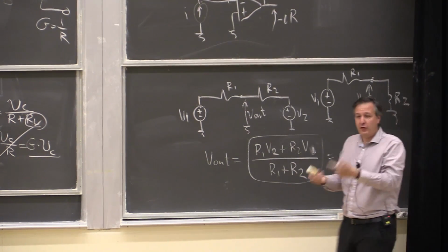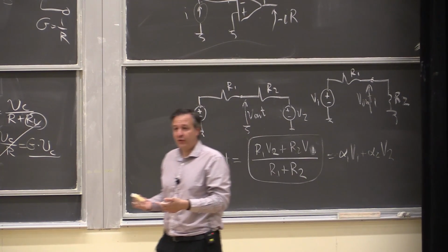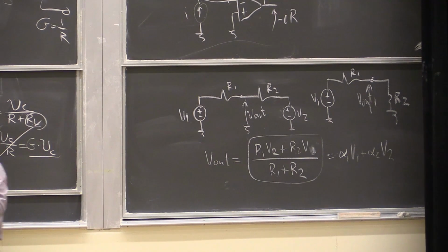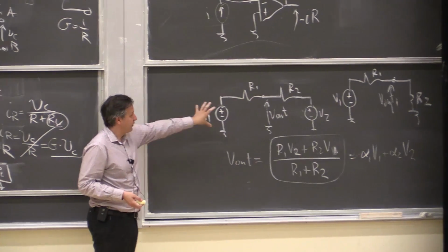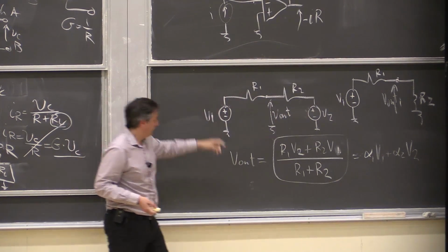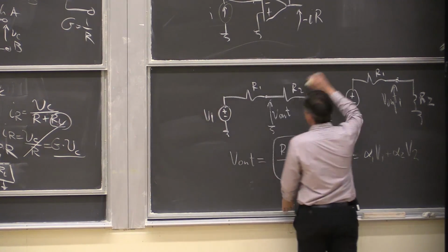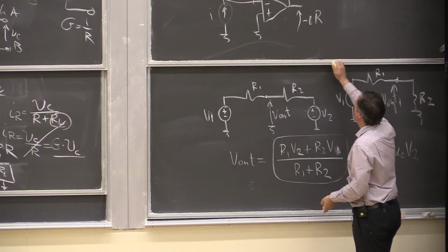So if in your problem you're asked for coefficients that are greater than 1, you need some sort of amplification, either before, if one of the coefficients is greater than the other, or after, so that you can gain everything up. So there are some small things to think about. There's another summer that you can use. So this one is just a pure summer.